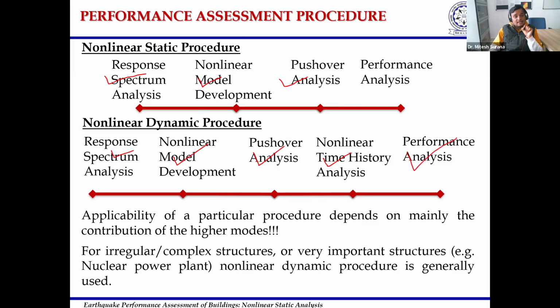It is essential and necessary to keep in mind that whenever we are performing nonlinear dynamic analysis, it is always advisable that we should also perform a nonlinear static analysis, because it is relatively easy to understand the response that we obtain from a nonlinear static analysis as compared to the response that we obtain from nonlinear dynamic analysis. So when we obtain the response from the nonlinear static analysis in advance, before conducting the nonlinear dynamic analysis, we get better insight into the behavior of the structure, how it is going to behave during an earthquake, and that helps us in understanding the results that we derive from the nonlinear dynamic analysis. So it is always advisable to conduct the pushover analysis first, then only go for the nonlinear time history analysis.